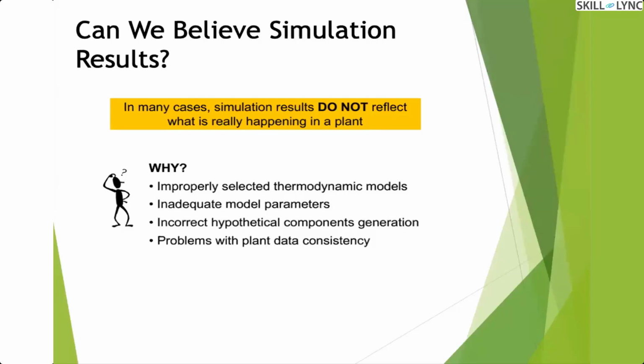So it is your responsibility to first check the XY plot and see whether any azeotrope is going to form or not, and only based on that can you determine the number of stages. So always your judgment and your values are important, because you cannot blindly go with the simulation results. Your procedure should be correct, and your values should also be correct. Another problem, like I have explained in the earlier slides, is selecting the proper thermodynamic package.